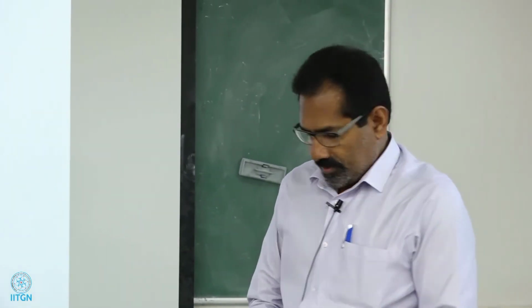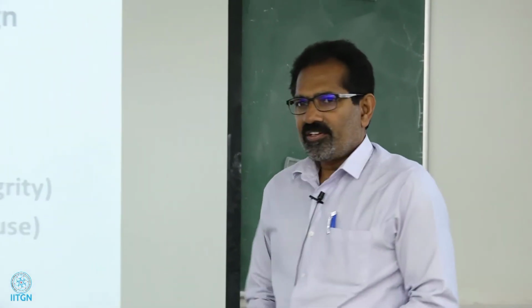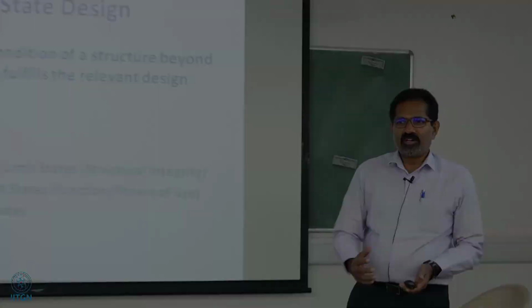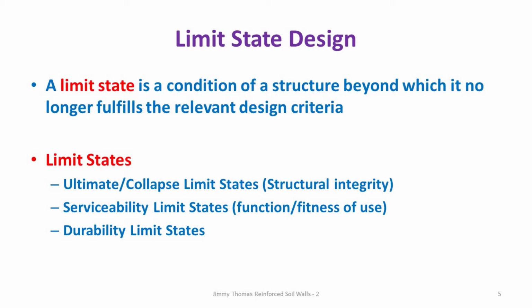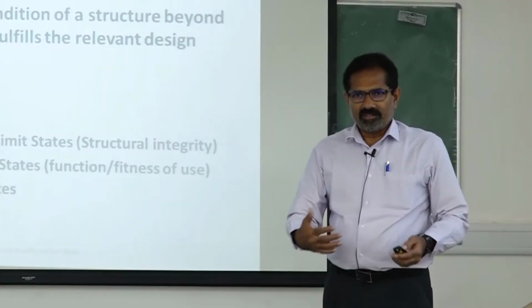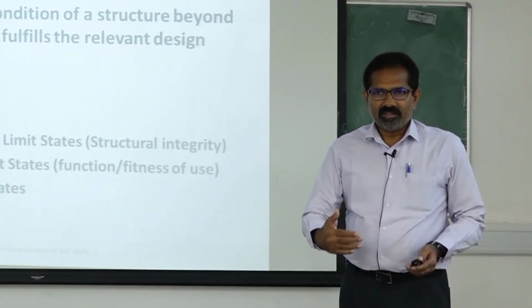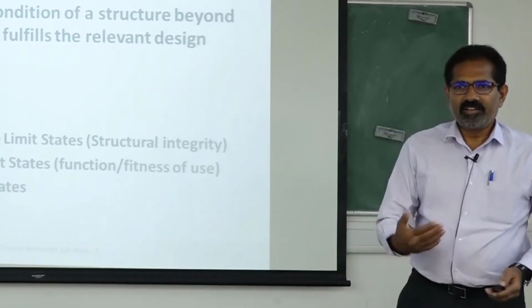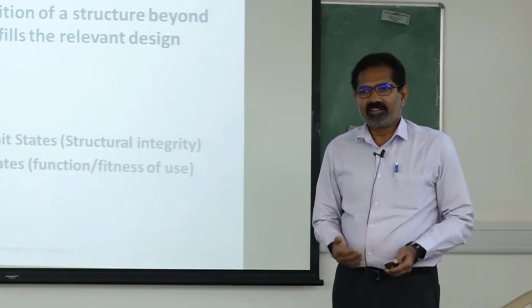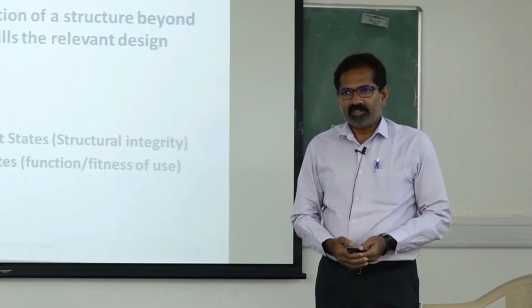Then the second is, the structure doesn't collapse, but it deforms too much, or vibrates too much, so it doesn't satisfy the function it was built for. Then third is durability. It is stable, serviceable, but then it corrodes or degrades. There is too much maintenance. That also doesn't serve the purpose.